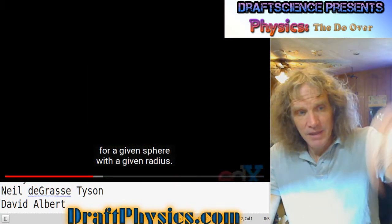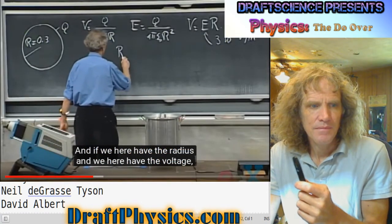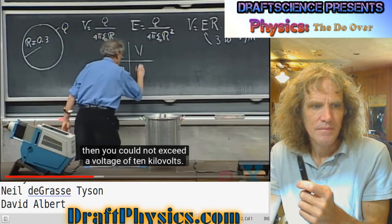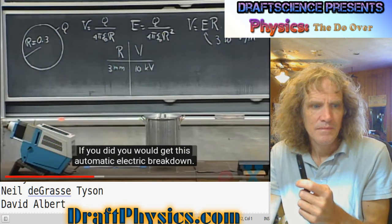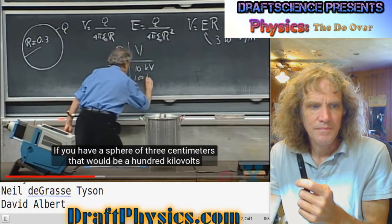If we here have the radius and we here have the voltage, then if the radius of the sphere were 3 millimeters, you could not exceed a voltage of 10 kilovolts. If you did, you would get this automatic electric breakdown. You would get a spark. If you have a sphere of 3 centimeters, that would be 100 kilovolts.